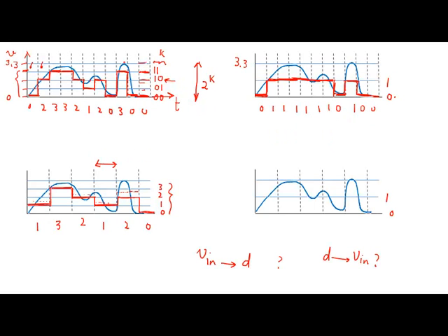Let me go back to the previous slide. If your signal level is here as opposed to here, it's not going to detect it. So it's very coarse in terms of detection, and it's even worse here. It's not going to detect any difference from here or here or here. If your signal changes very slowly, and in the next level it's here, and then it falls down just a little bit, for all of these you're going to read the same thing.